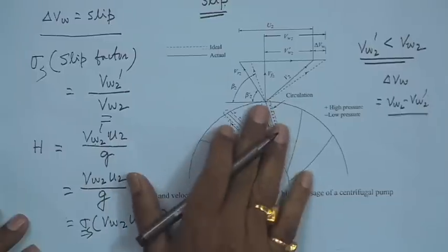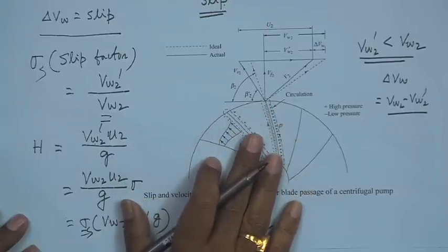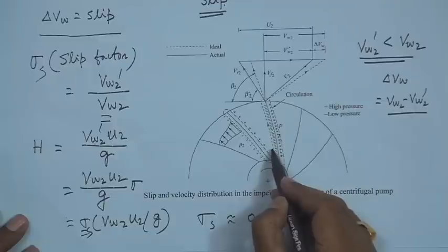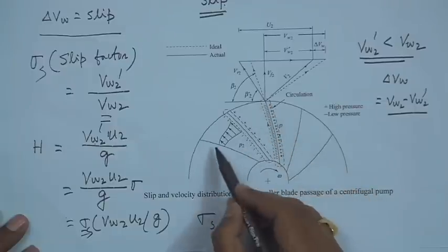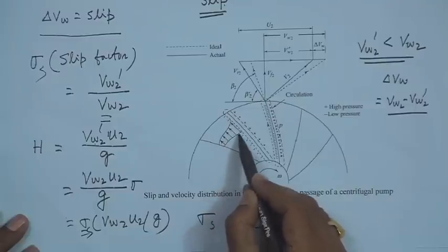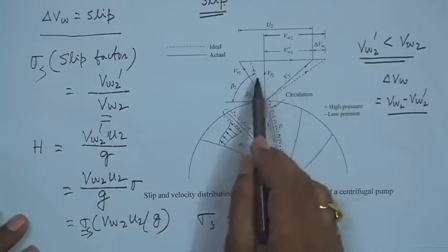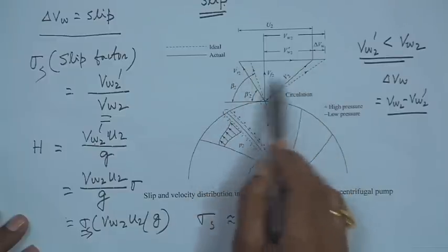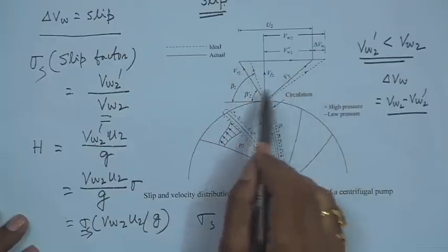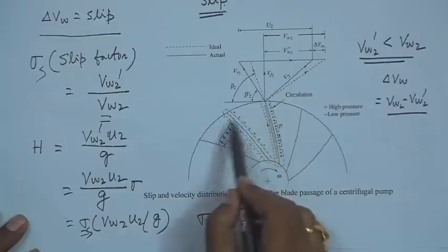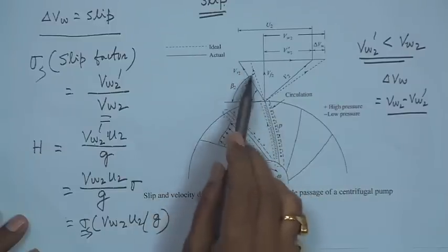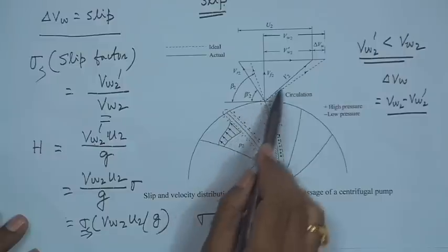This is because of the blade curvature, which induces pressures which are different on the leading and the trailing faces, and creates the circulation for which the velocity distribution becomes non-uniform and makes an alteration in the velocity triangle from that of the ideal one. Actually, the velocity triangle we draw changes the direction of the relative velocity from that of the actual blade angle, for which everything changes.